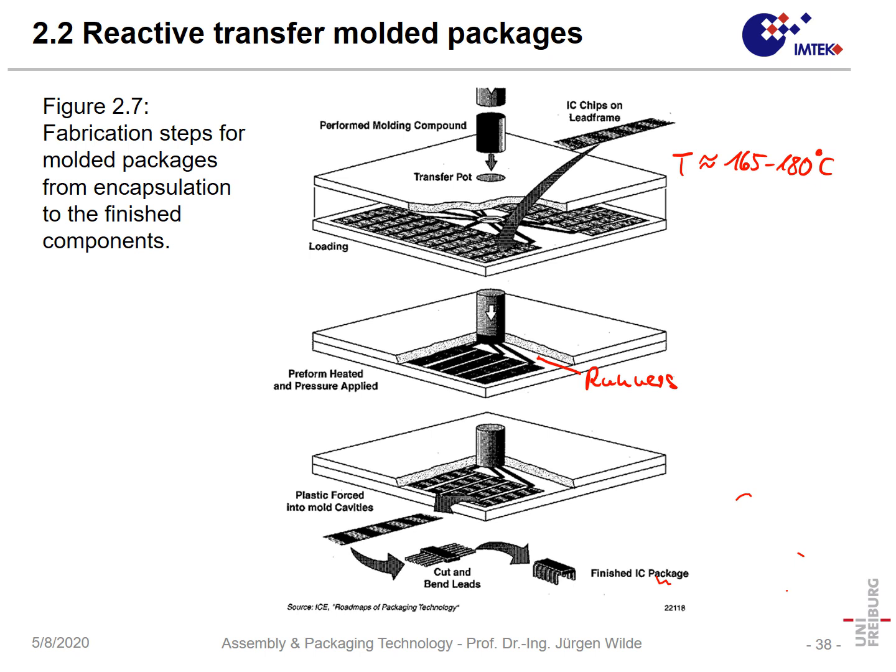So that means the packages are still together on a lead frame, and after that the lead frames are taken out. The leads are cut with some automated tool. They are bent in order to form through-hole legs or surface mount device legs, and so devices are produced.